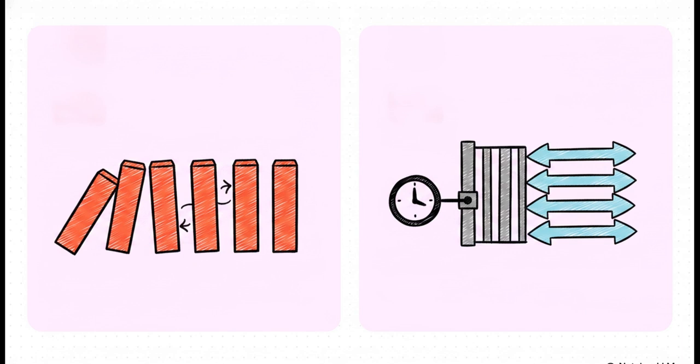A favorite insider test is asking you to explain exactly when to use blocking assignments with an equal sign versus non-blocking assignments with a less than equal sign in Verilog. Answering this one correctly proves you understand how to avoid simulation race conditions, and it shows you know how the simulator actually evaluates sequential versus combinational logic.